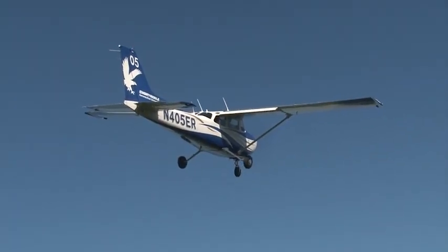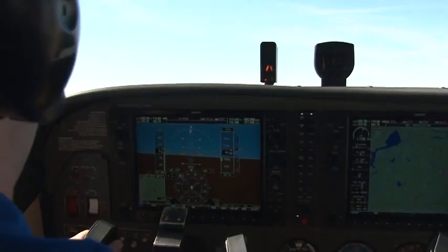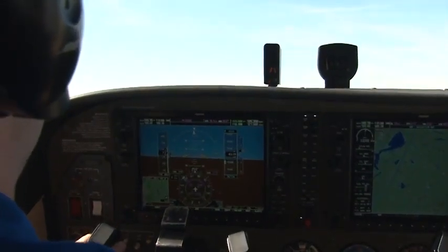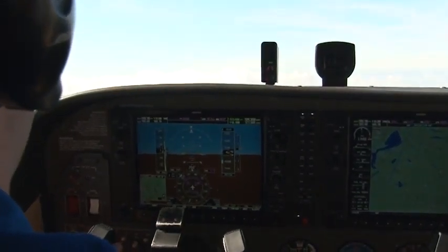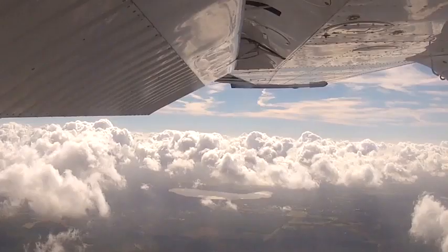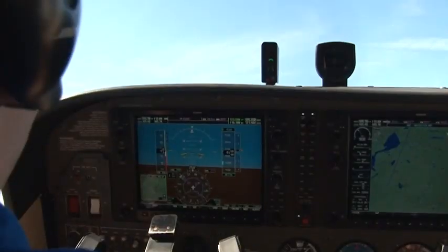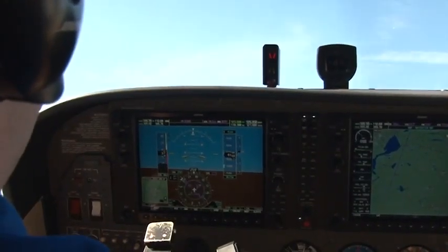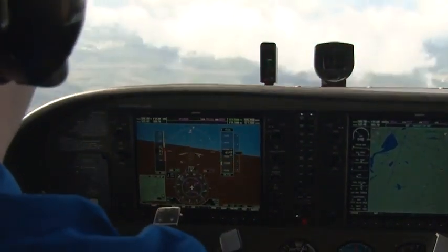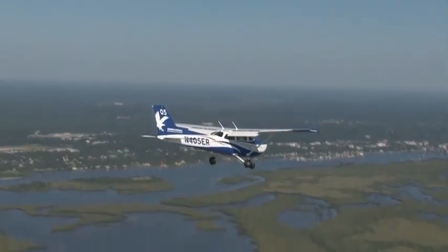Different airplanes will exhibit different stall characteristics, but generally coincide with mushy, sluggish flight control responses, a stall warning horn, a buffeting or shaking feeling of the airplane and pilot's controls, and once the stall occurs, the aircraft's nose will pitch down and the aircraft will begin losing altitude.